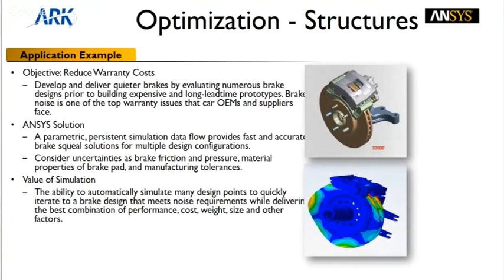So what was the ANSYS solution given for this particular case? We developed parametric and persistent simulation data which provided a faster and accurate brake squeal solution for multiple design configurations. The parameters on which we did the optimization study were brake friction and pressure, the material properties of the brake pad, and the manufacturing tolerances. We took all these aspects into consideration.